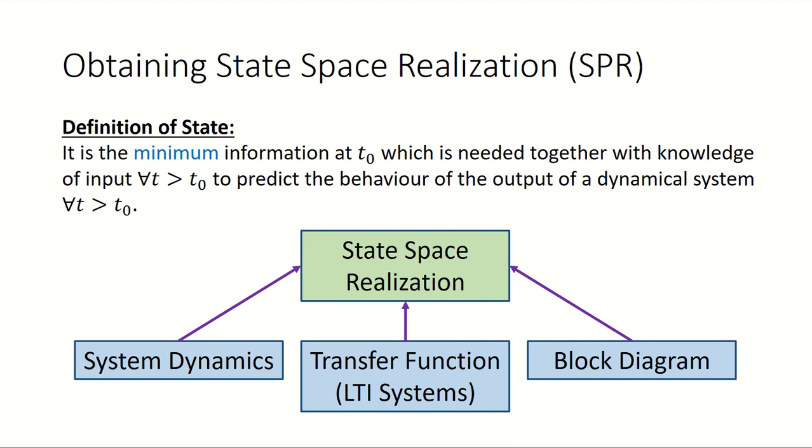So if you have a system already represented in block diagrams, you will be able to derive the state space realizations, and hopefully you already have some hint how to do this, as I discussed in the last slide: integrators and gain blocks and summers. Those will also be taken up in detail. So if you have a block diagram representation, you can create a state space realization,